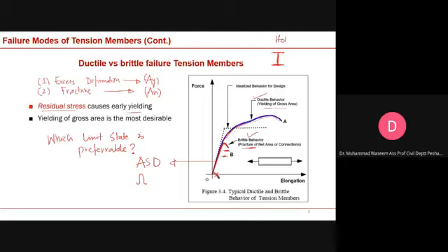So compressive and tensile stresses will be produced in your member before application of the load. When the load is applied, the tensile stresses in the member add to the stresses produced by the applied loading.